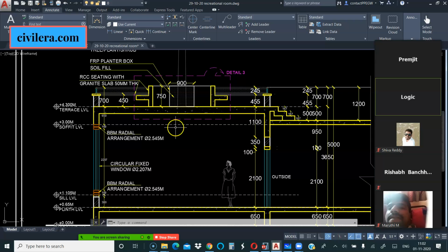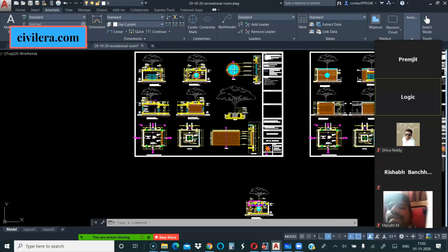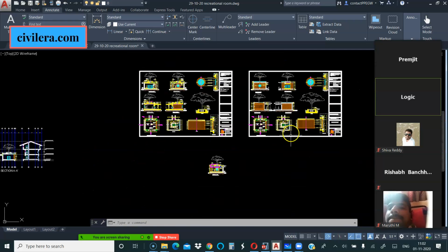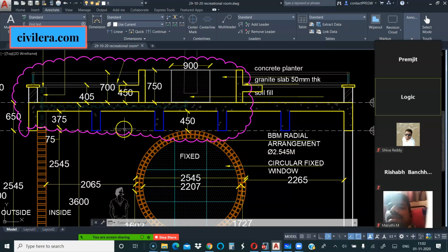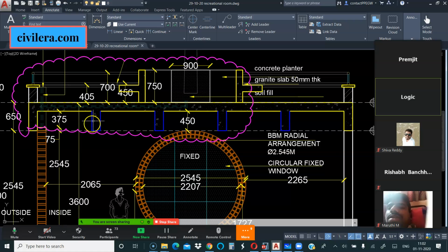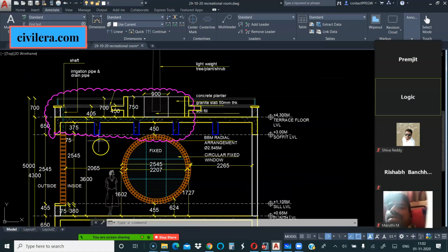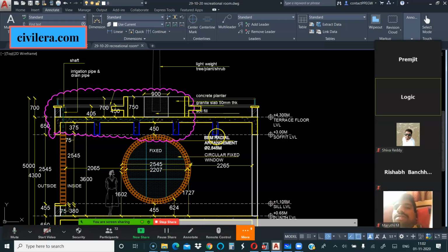Then finally, I proposed a kind of grid slab where on equal spacing I gave beams, so that was acceptable to them. So this is the section. You can see a beam, a beam, a beam. When you imagine it, when you are inside the room and looking up, you see a kind of grid. That was better for them than having a single or two beams here. So at regular intervals, I give many beams and achieve the structural requirement.